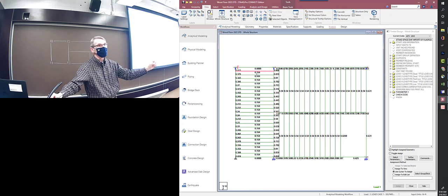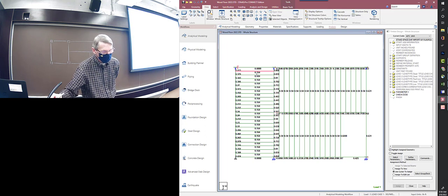And I could go to the table and pick it by the section modulus. So you could actually pick it like that. In the case of the joists, there are not that many choices, right? I mean, we're not going to go less than a 2x6. So that's a 2x6 or a 2x8. Those would be the only two choices. So you might as well just pick one.